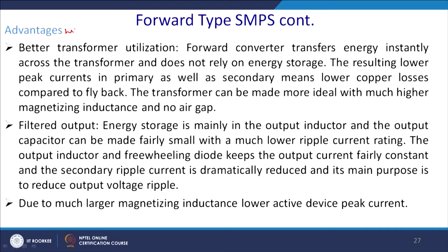Advantage with respect to flyback: better transformer utilization. The forward converter transformer transfers energy instantaneously across the transformer and does not actually store the energy.